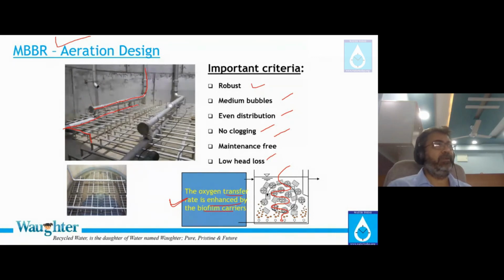Because you cannot give air like a Z. I'm just making this sound. You cannot give air like this, because if you are giving air like that and that air hits the carrier, what happens to my biofilm? Biofilm will be immediately sloughed off.